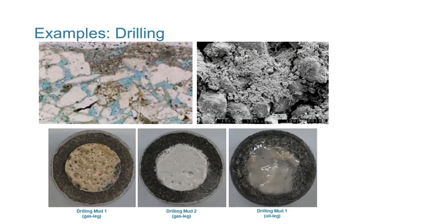And it's quite clear why, because we can see that after the mud built up and we started to produce, lots of channels, wormholes, opened up in the oil-based mud cake. So essentially it wasn't having an impact on permeability at the end of the production. Whereas with the water-based mud, just a few of these channels, much bigger drop in permeability because the cleanup was poor.